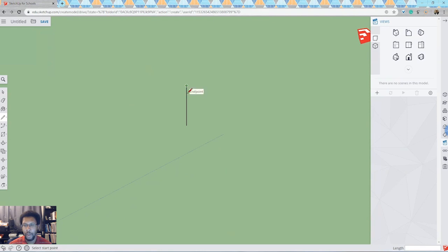Next we're going to go over here to the endpoint, and we're going to draw a line. We're going to draw this so that it's about, let's say, 75 millimeters. So we type in the number 75 and hit enter. Then we're going to go down here and make the first part of our letter.